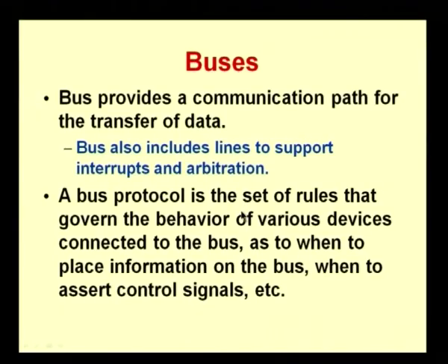A bus protocol is something that we also have, which is a set of rules that governs the behavior of various devices connected to the bus as to when to place information on the bus, when to assert control signals and so on. When can data be placed on the bus, when can data be taken from the bus, all these things are controlled by means of a bus protocol. So, whenever we have any bus that is designed, we would normally have a protocol that goes with it, which we need to understand to see how exactly data will be transferred from and to the bus.